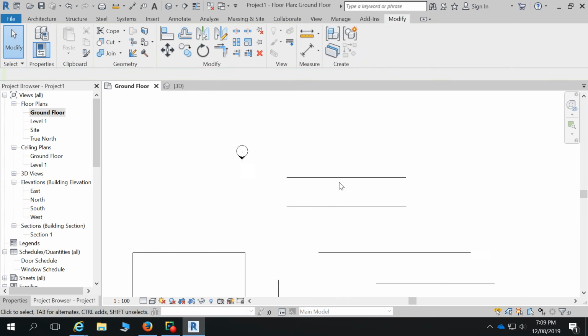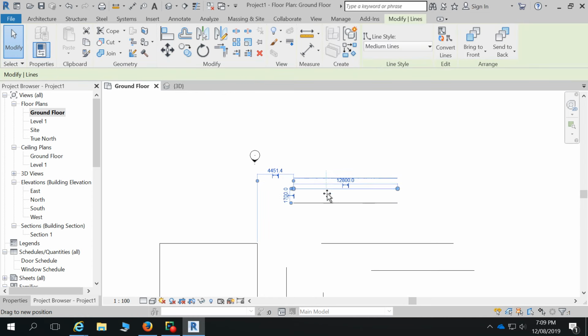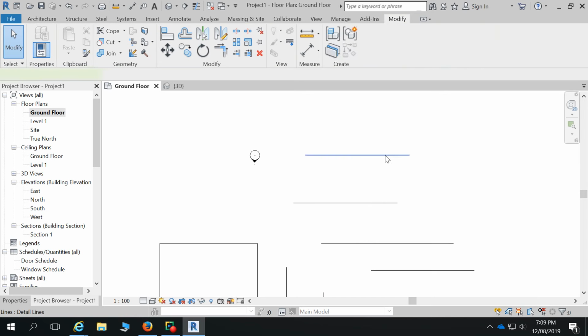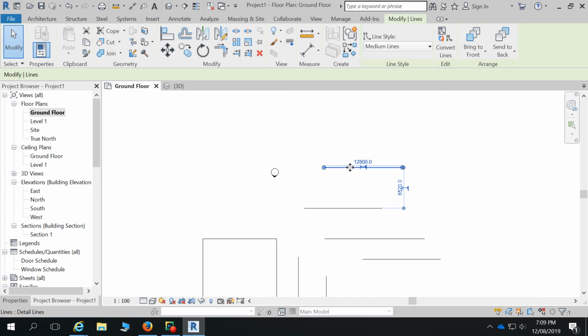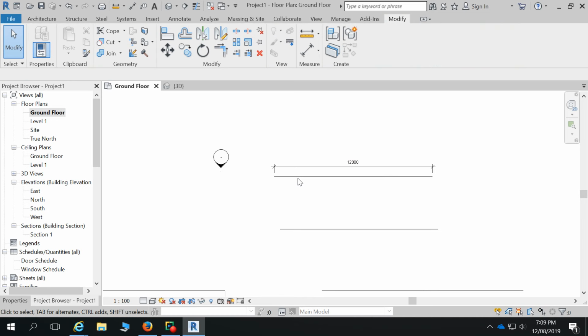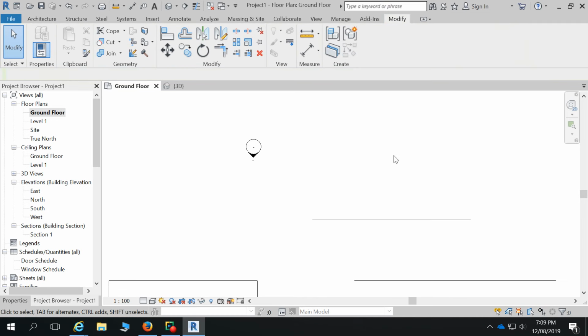The other way we can move items, I've just hit escape a couple of times to get out of that command, is to actually click on a line, and you'll notice if I just left click, I've actually just grabbed that line with my cursor and the move tool is actually working. So you can click and just do an accidental drag and move. So it is a bit unpredictable sometimes, that tool. I don't really like it. I wish it didn't do that.